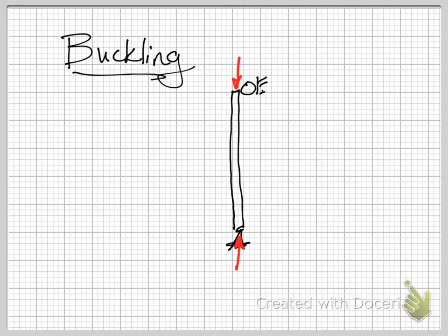Buckling occurs when this axially loaded compression member is loaded to a point where it experiences an instability, a structural instability, and a sideway motion, causing the member to bow out. Buckling is a behavior. It's neither good nor bad by itself, but it's a behavior and a phenomenon that, depending on where it's exhibited, can either be catastrophic or it can be used for good. Here's some examples.